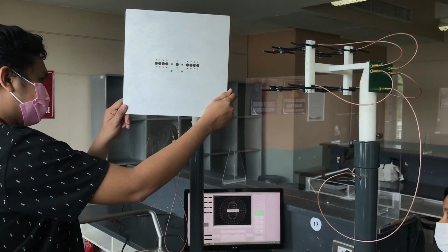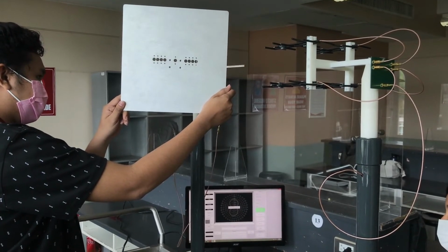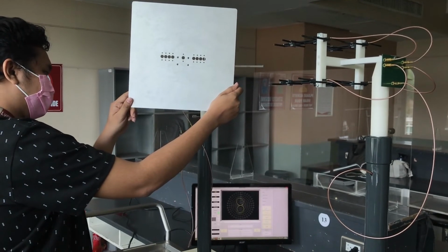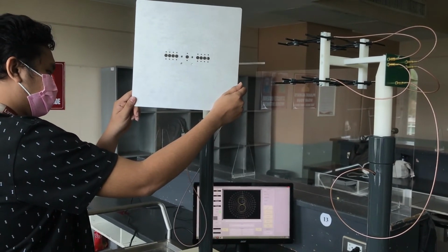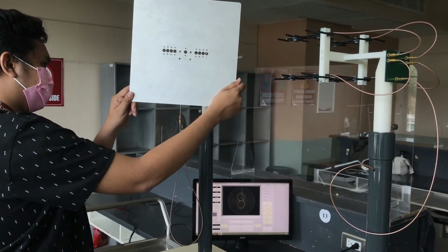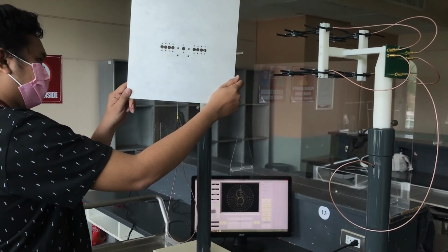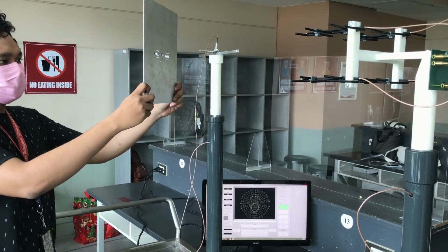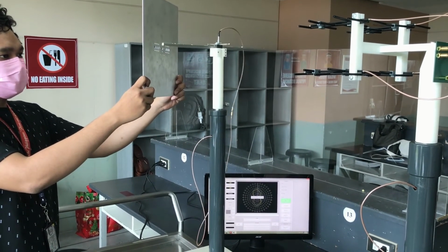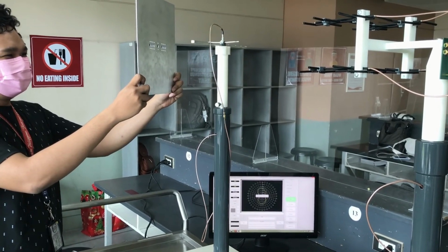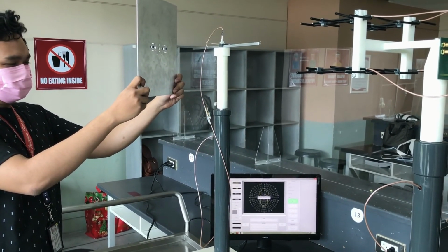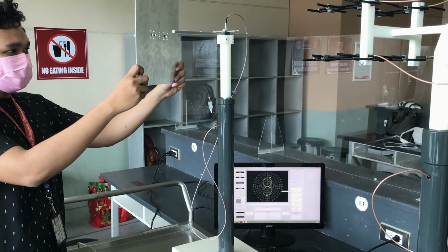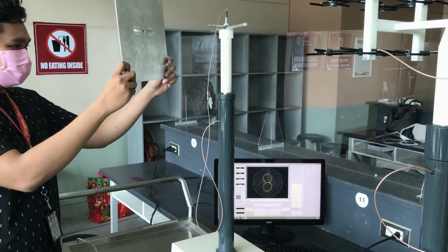There were two notable metal sheet positionings during the experiment. First position is when the metal sheet is positioned directly in between the transmitting antenna and the receiving antenna. The maximum and minimum RSL of the system under this condition was reduced by at least 43% and 20% respectively. Second position is when the metal sheet is placed in the opposite direction of the receiving antenna. For this condition, the measured maximum RSL was increased by 12.55% and the minimum RSL was reduced by 15%.